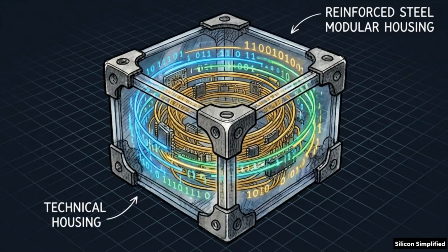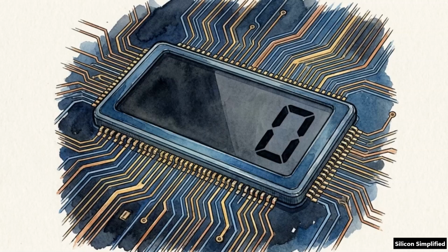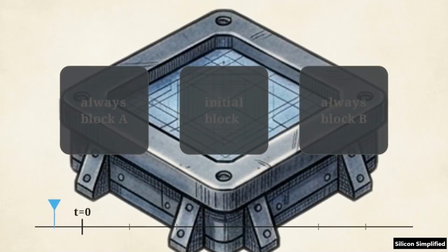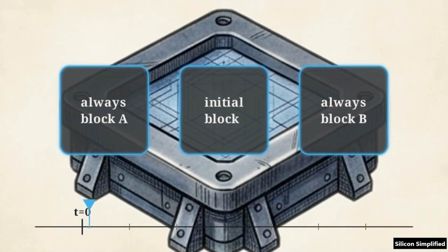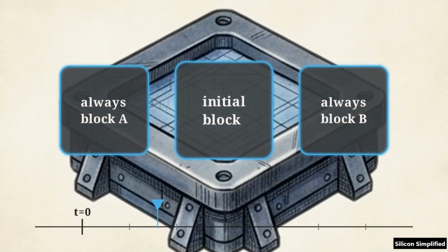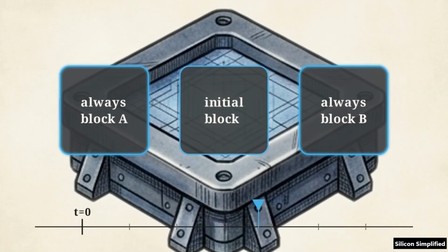The highest level of behavioral abstraction in Verilog is the procedural block. Think of it as an independent container for a standalone hardware process. Every simulation begins at a primordial starting condition, known as time zero, or t equals 0. Unlike C functions waiting to be called, all declared Verilog procedural blocks wake up and trigger concurrently at time 0. There are two main types. The first is the initial block. It runs its statements exactly once, then terminates.